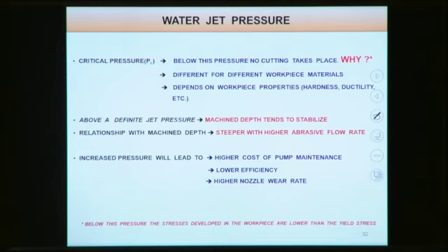Increase in pressure also means, as we have seen, that with the increase in pressure, your metal removal rate or depth of cut increases, but only up to some optimum level of pressure. Beyond this critical pressure, what happens? There is a decrease in metal removal rate.